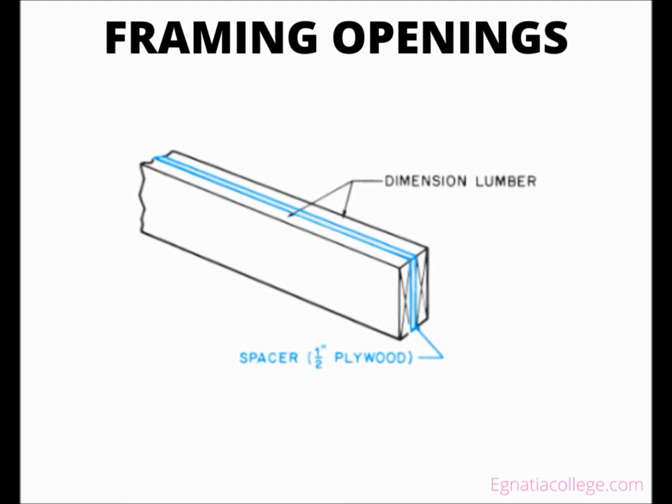A set of construction drawings includes details showing the type of rough opening construction intended. It has been conventional to build headers in exterior walls with 2 by 10 or 2 by 12 and plywood spacers between to form the header. A flat 2 by 4 may be nailed to the bottom of the header to reduce the height of the top of the opening, but this flat 2 by 4 is filler and not a structural part of the header.